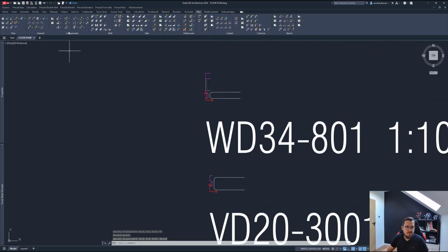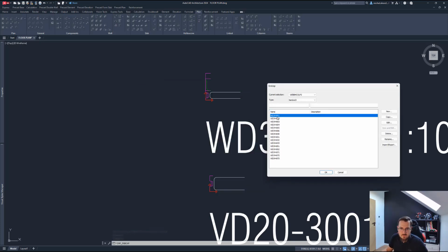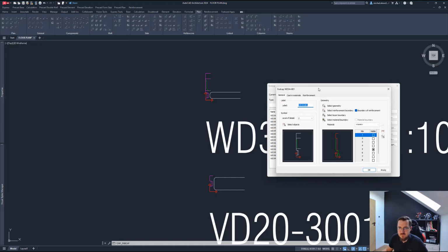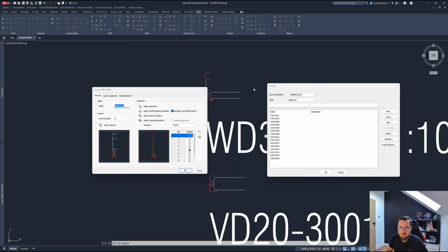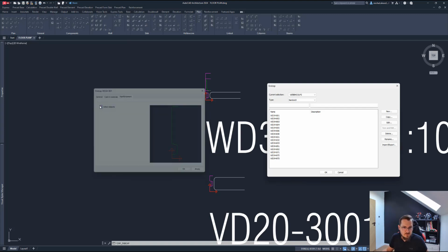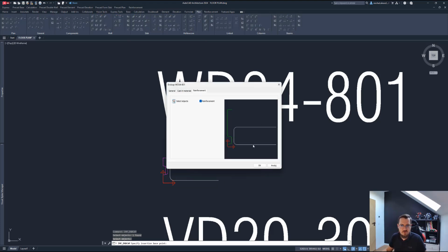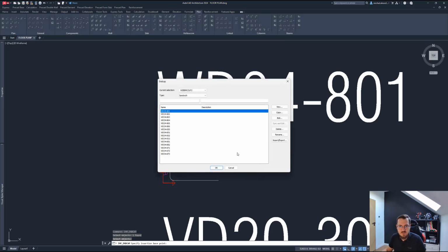Now let's go back to plan and let's edit the end caps, because this is where you actually edit the reinforcement in the end caps. I'll open up the first end cap. So that's the 801 end cap, right? And here I have some specification of the geometry of that, the extents of the end cap, the casting materials if any are placed automatically, and the reinforcement. So let me select the objects for this particular end cap, 801, and let's select the reinforcement. And the base point, which will be this point. And we get the preview of that. And that's it. I'll just accept that and save that.